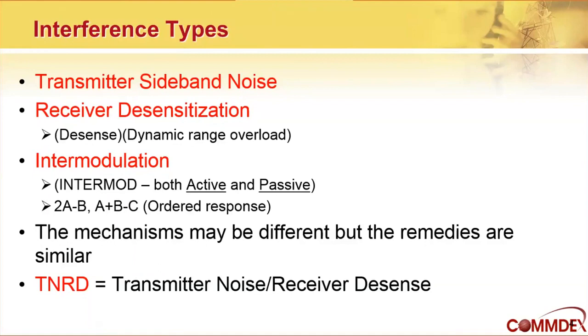And a third type of interference most of us are familiar with, intermodulation. This is a type of interference that is generated either on site or away from site. The 2 types of intermod are active and passive. Active means it occurs in an active device, something that has an amplifier or electronic component to amplify the signal.